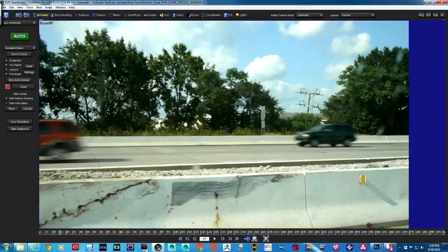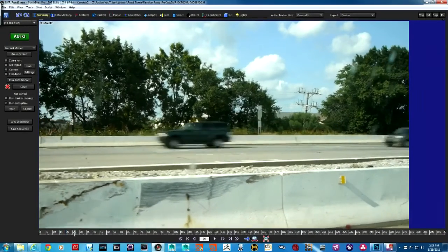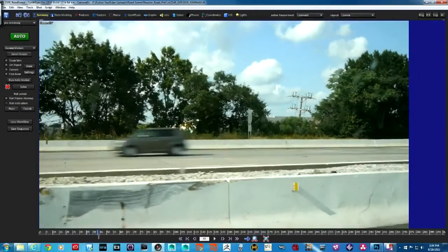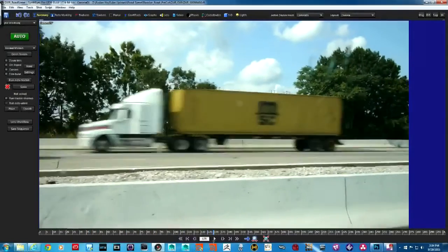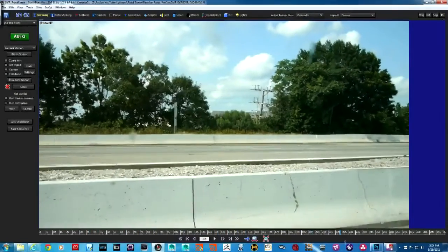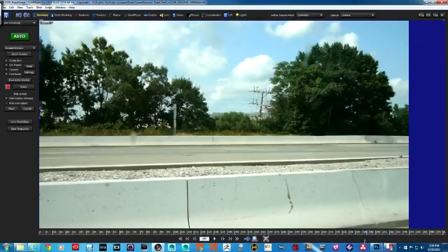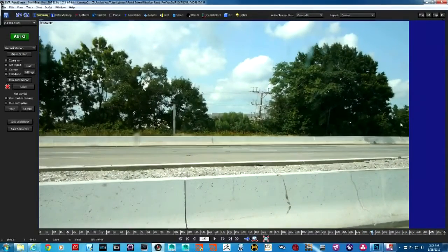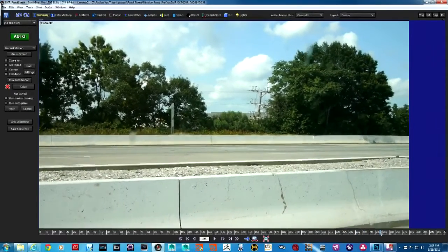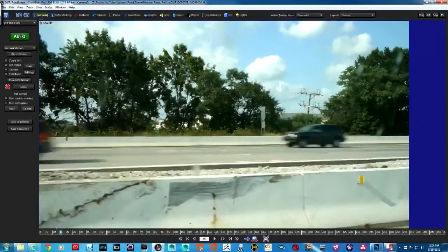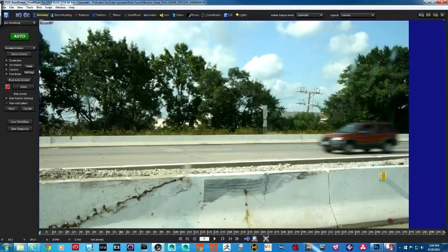Yeah, so these leaves here you will see as I play, they are moving around because of the wind, and that would get in the way because when you are tracking the camera, you shouldn't have any moving object that is also getting tracked. You can see here there's quite a bit of motion there, and we want to be mindful of that. But okay, let's start with the auto process, but in there I'm going to break it down. I'm going to fine tune. Let's run the tracker first.